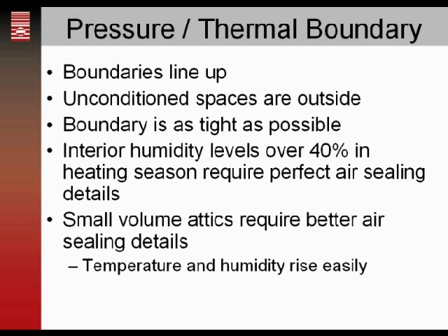And anytime you add roof venting, you're going to increase your blower door number. Roof venting becomes less of an issue as you make the boundary tighter and tighter. You don't need as much attic venting to get those pressure boundaries and thermal boundaries to line up. Whenever you have high interior humidity levels, and I would consider that over 40% during the heating season, it requires perfect air sealing.